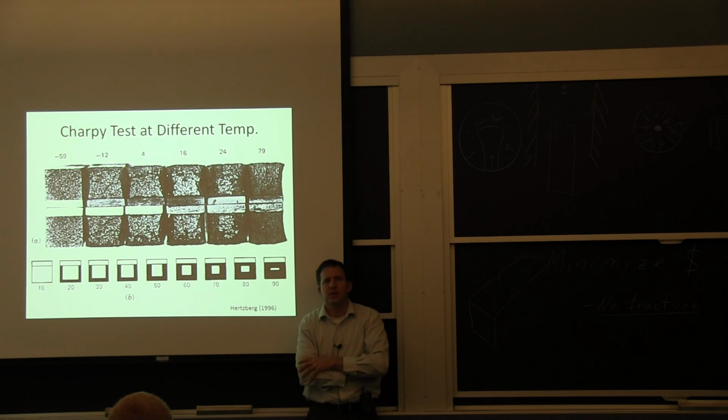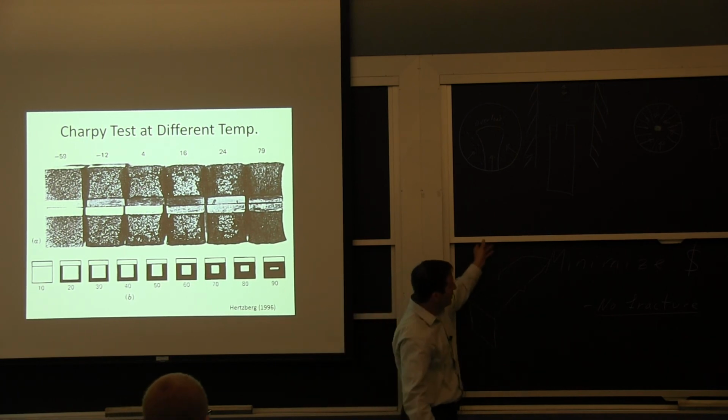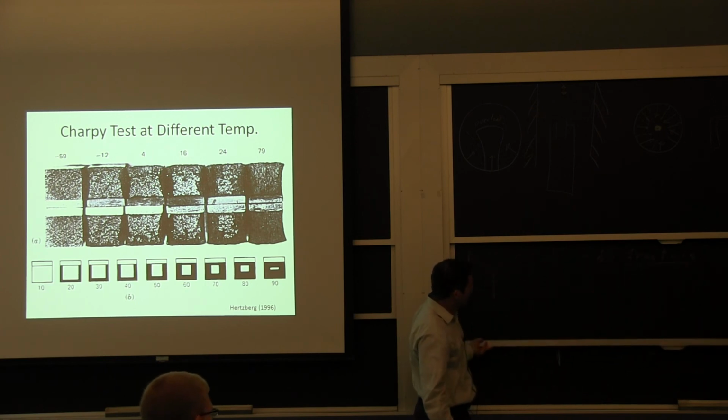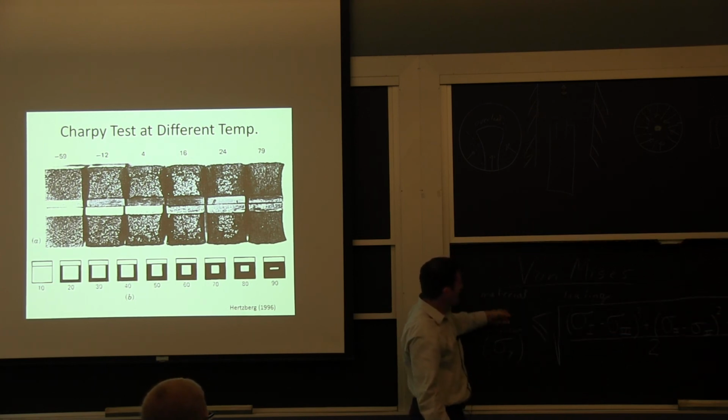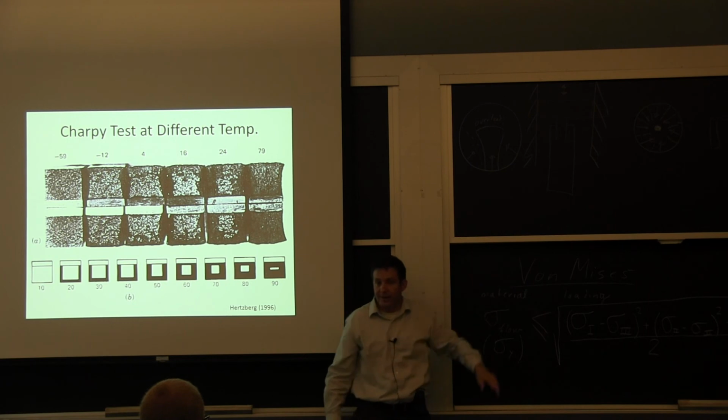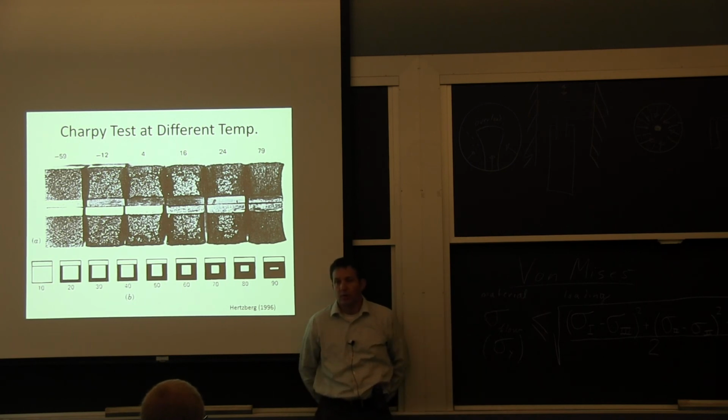Tin came in because we were working on a solder joint, and around minus 100 degrees centigrade is where tin essentially starts having this curve peak right up, and you have more of a reduction in ductility, and you have a very brittle behavior.